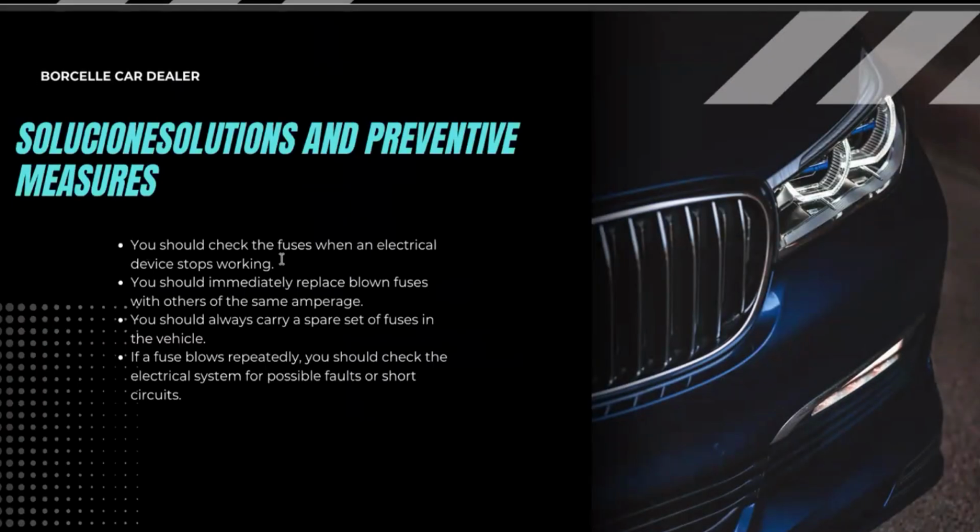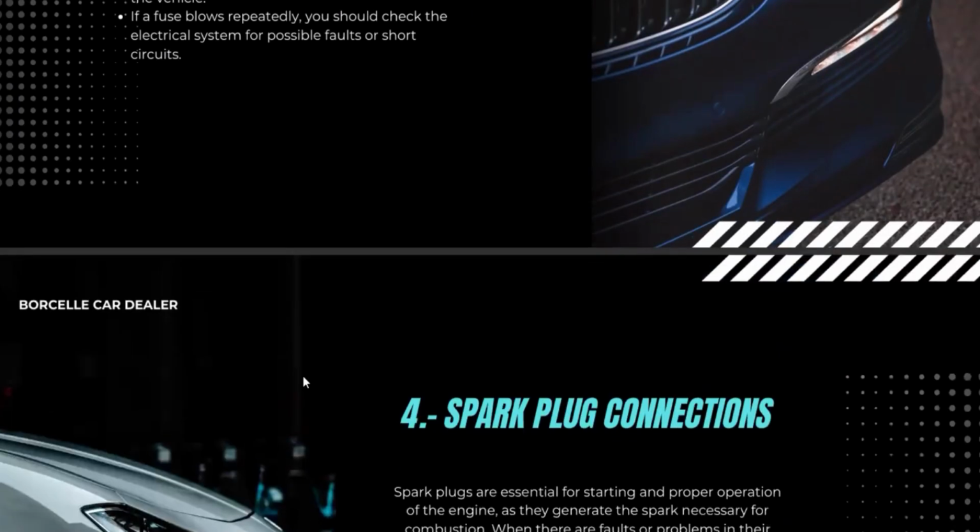You should check the fuses when an electrical device stops working. You should immediately replace blown fuses with others of the same amperage. You should carry a spare set of fuses in the vehicle. If a fuse blows repeatedly, you should check the electrical system for possible faults or short circuits.